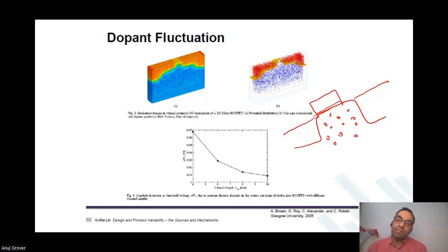It can also happen that instead of 20, there are 18 dopants. Now, less band bending is required for VT to be there, and therefore you will see that the device is a little fast. Are you with me?